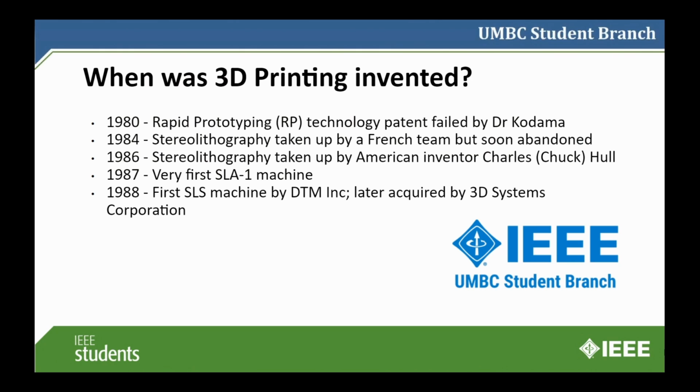It would break down the material into G code, or instructions, and then harden the polymers with that laser. Same thing for the SLA machine or SLS machine, where SLS stands for Selective Laser Sintering, which is similar to stereolithography and almost resin 3D printing, but it's layer by layer melting of a plastic powder.